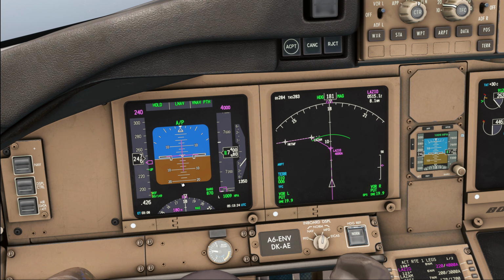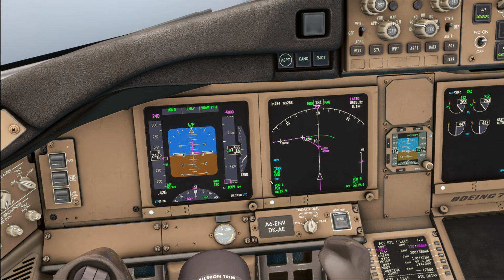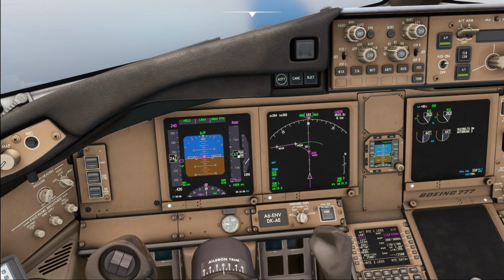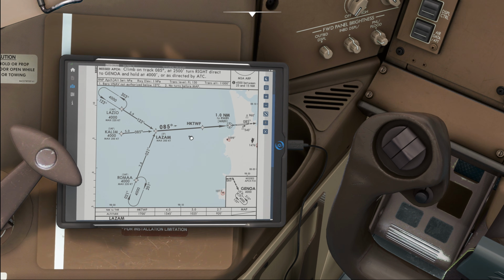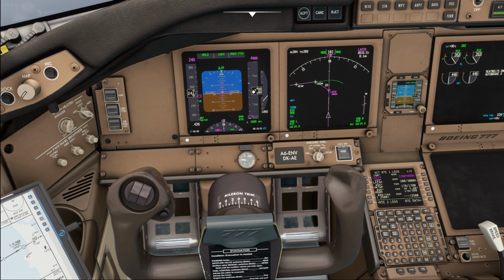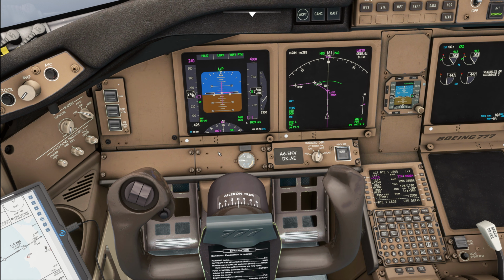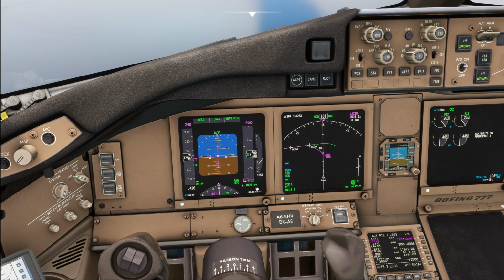And remember that if you approach over land and not over ocean, then you never know if you might have rising or falling terrain, so it can be very hard to detect errors based on the radio altimeter alone. However, nonetheless, always compare your indicated altitude with the radio altitude, taking into account airfield elevation and the terrain profile prior to the runway. For example, today we're approaching over the ocean. For that reason, if the altimeter indication and the radio altimeter indication disagree from one another, that is a clear indication that we have an altimeter setting error.